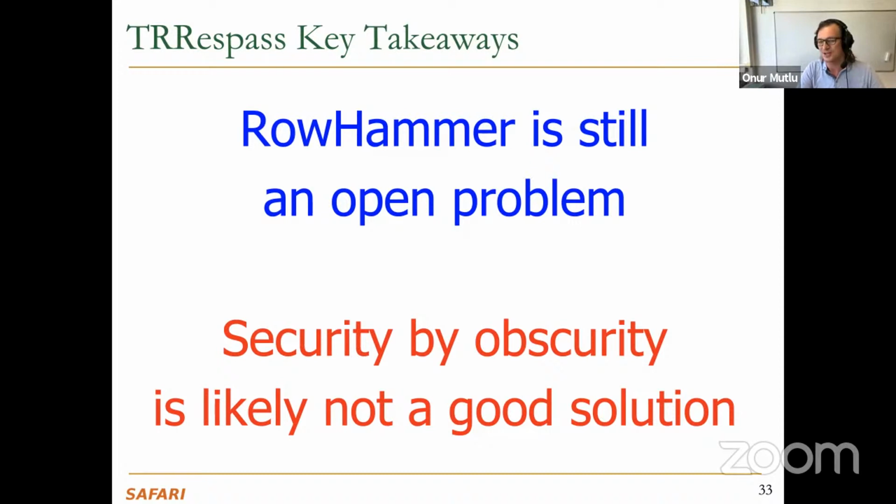And I picked on RowHammer because RowHammer is a specific example of what's known more generally as fault attacks. People have looked at what's called fault attacks. Essentially, you induce a fault, hardware fault. It could be a software fault also, but let's say a hardware fault. And you basically trigger the attack based on that fault. And that fault can be a single bit flip. That fault could be something else also, potentially a failure of a DRAM chip, right? Complete failure of a DRAM chip. But a bit flip is usually easier to exploit.